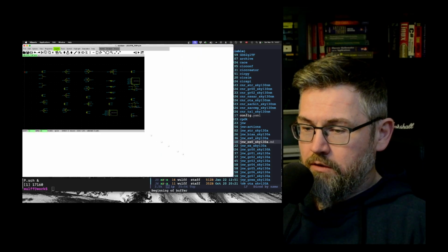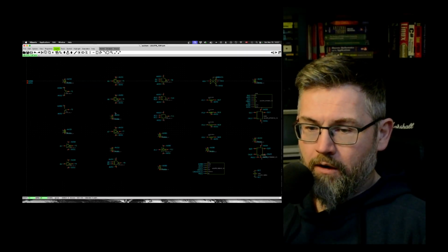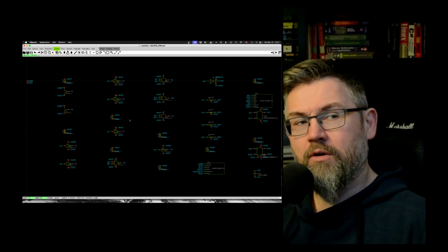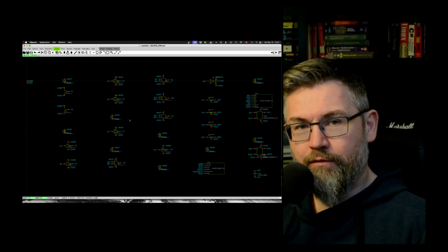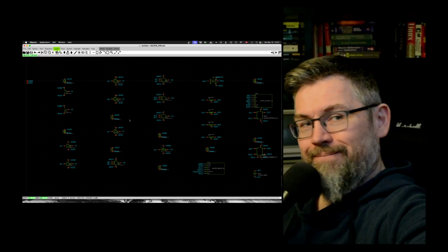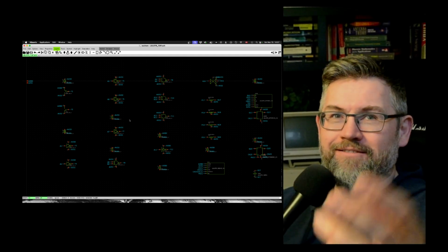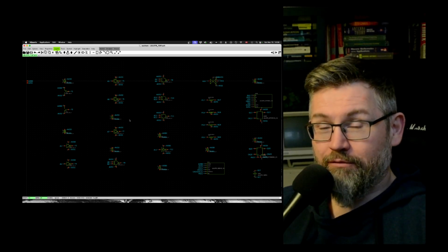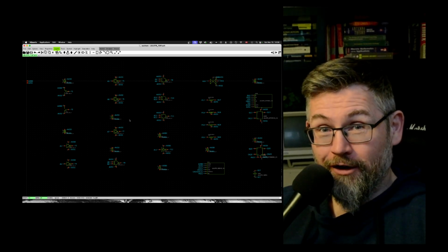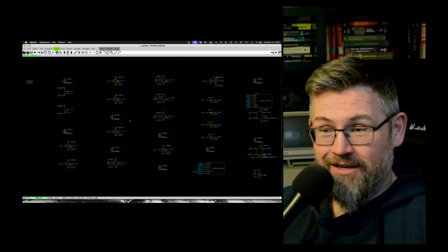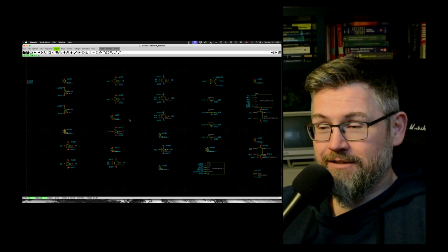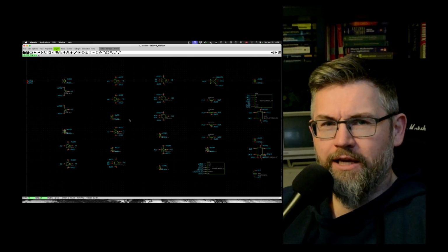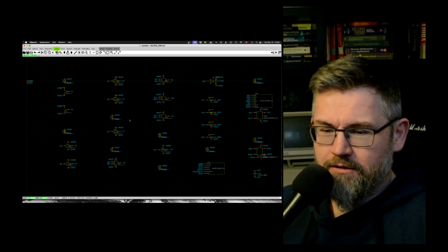So inside this library, I have sort of the standard cells that I use. These are not made for place and route. So if you're doing automatic place and route from digital, this is not the library you want to use. The library is quite big transistors. It's made more for the stray logic that you need in your analog designs.